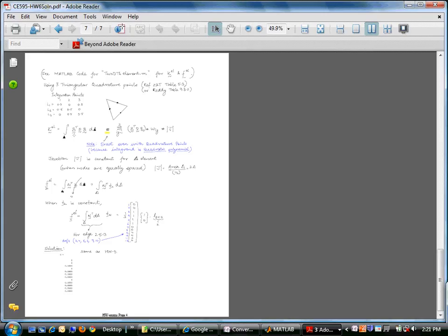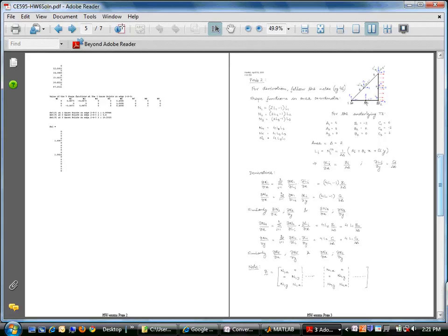What would be the terms in the B matrix? Okay. So the terms in the B matrix are all these. These are the shape functions, derivatives with respect to x, y. And each of those terms is going to be linear in L1 or L2 and L3. When you take B transpose dB, you will get something that is quadratic.